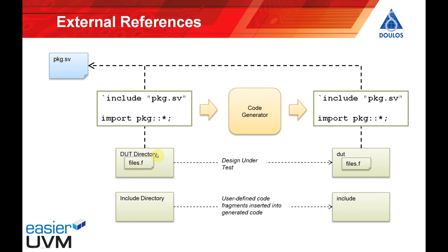So if within SystemVerilog files in the DUT directory or the include directory, you have any include directives or you import any SystemVerilog packages, then those include directives and imports will just be copied one for one into the output file set.